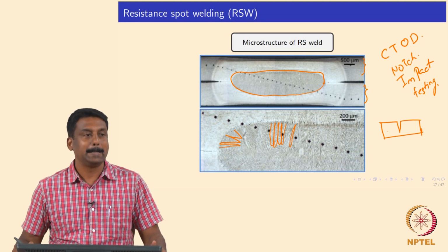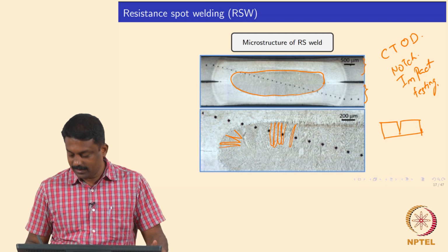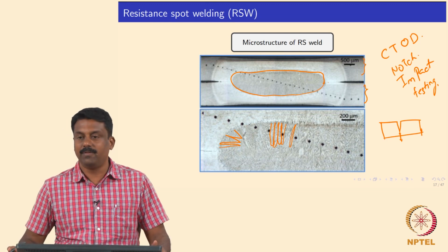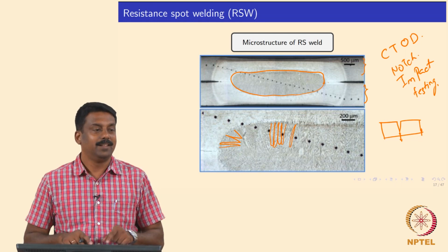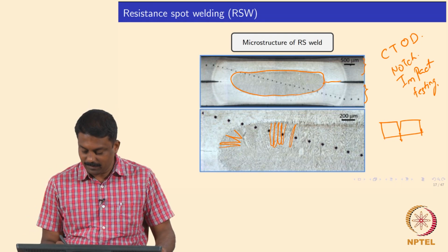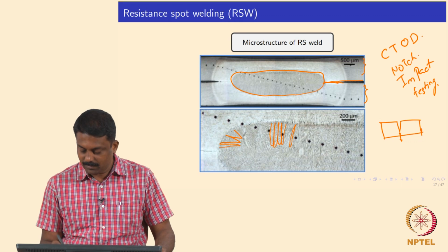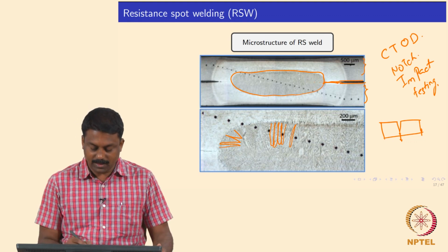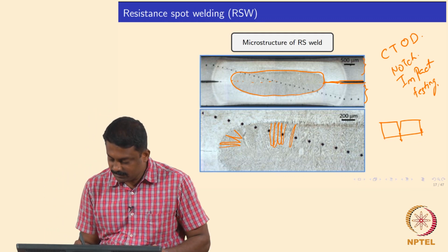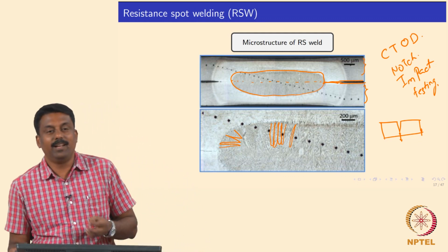Something like this. So you'll have stress concentration leading to a failure. And if you look at the structure, it's exactly like that. So you'll have a notch, right, and then a segregation at the center line, and this is a potentially very vulnerable structure,